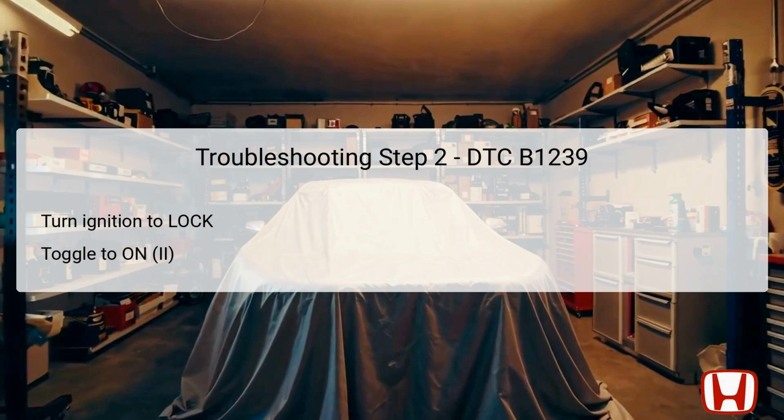Following the clearing of DTCs, the next step involves a simple yet crucial action: turning the ignition switch to the lock position, then back to on. This process reinitializes the vehicle's electronic systems, including those managing the climate and mode control functionalities.